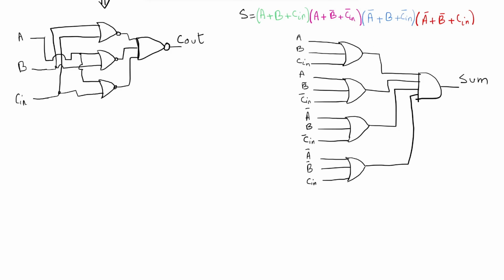So next, to convert this to NOR gates, we can add a NOT gate twice on the signal wire because this doesn't change the signal. And another one here. And similarly, this one here will be a NOR gate, and each one of these, an OR gate followed by a NOT gate, is a NOR gate. So now let's redraw our circuit. So here we have a NOR gate, the output is the sum, and then we have 4 NOR gates.